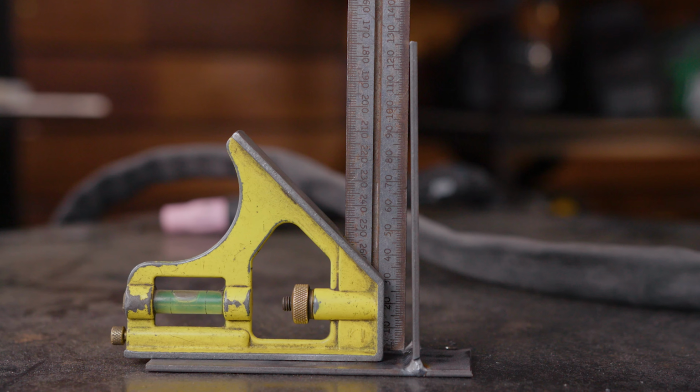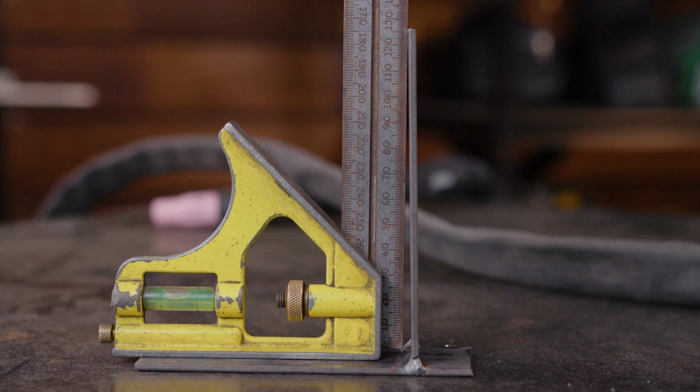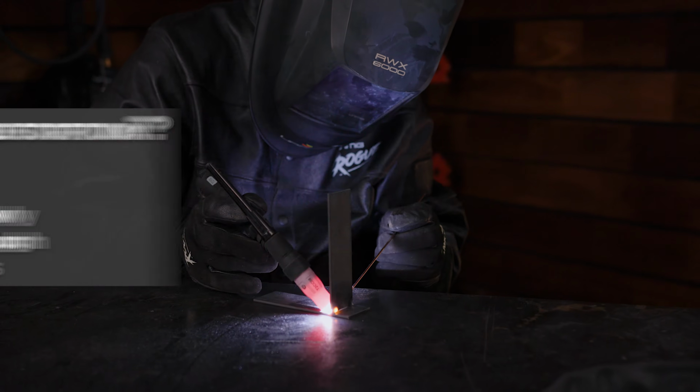Distortion can also be referred to as warping, in which the material hasn't been able to cope with the expansion and the contraction that comes with heating and cooling. It often looks as though the metal has begun to pull and warp. A lot of the time, it means that there's too much heat in the plate, not just the joint, which the metal can't handle. So what causes it?